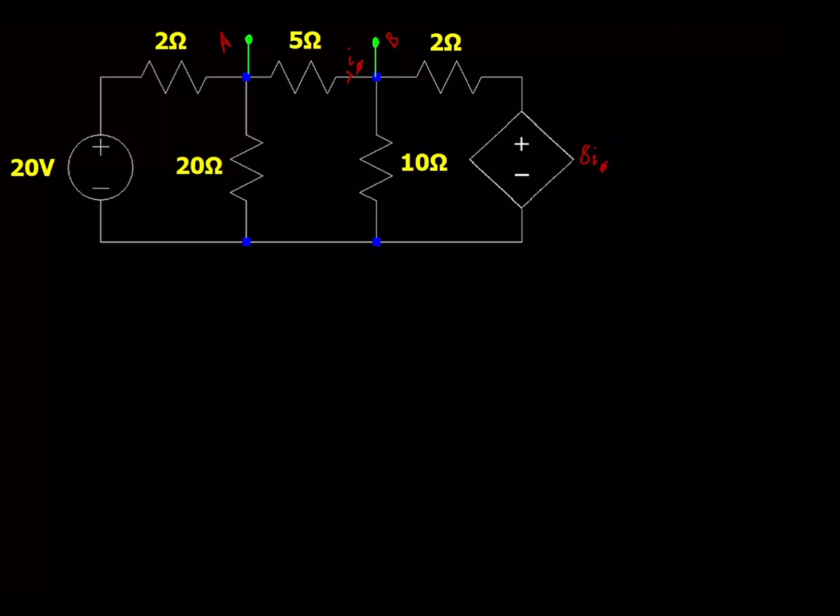topic I've covered previously. Again, we're going to try and get our Thevenin equivalent circuit. This time our terminals in question are A, B up here, the 5 ohm resistor terminals. So the first thing we need to find is that open circuit voltage, this Thevenin voltage here. And so we have to solve the circuit to do that. But instead, we're going to take advantage of source transformation topics.